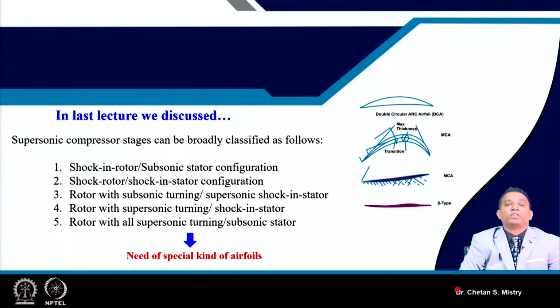Under off-design condition, when the flow strikes the sharp edge, the flow pattern or shock pattern we expect may not happen. Under subsonic condition, the whole aerofoil or blade may go into stall, and literally into surge condition, and we know surge causes catastrophic failure of our engine. So we need to be very careful in choosing aerofoils.